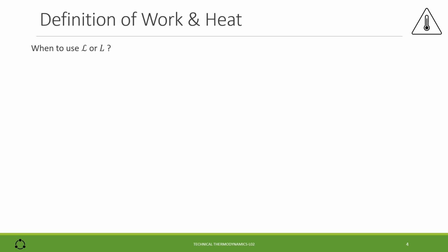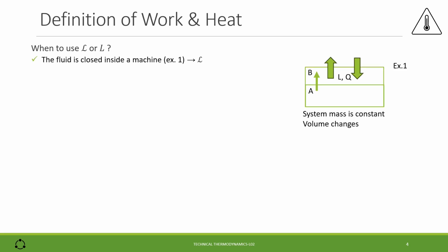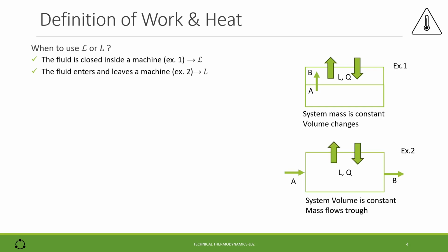When to use the thermodynamic or the technical work? If the fluid is closed inside the machine, like in the example number 1, we use the thermodynamic work. The system mass is constant, but the volume changes. If the fluid enters and leaves the machine, like in the example number 2, we use the technical work. The system volume is constant, but the mass flows throughout it.